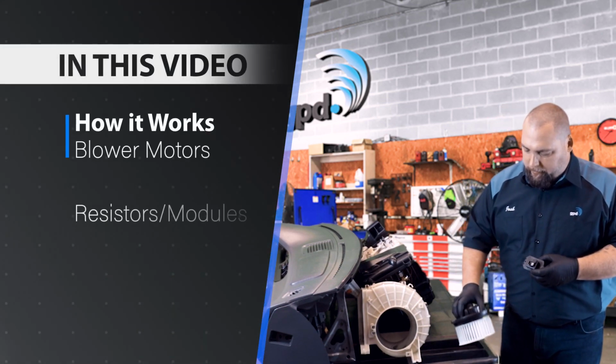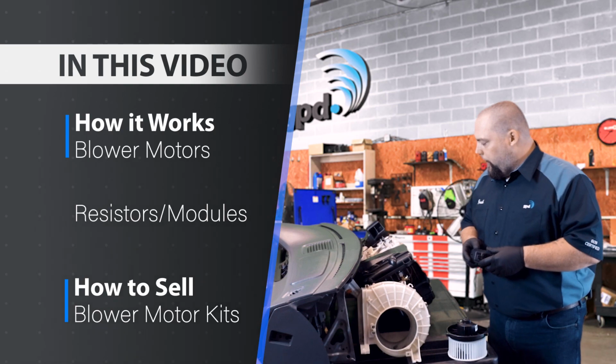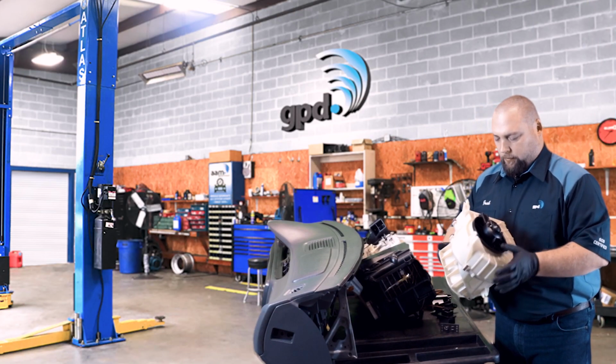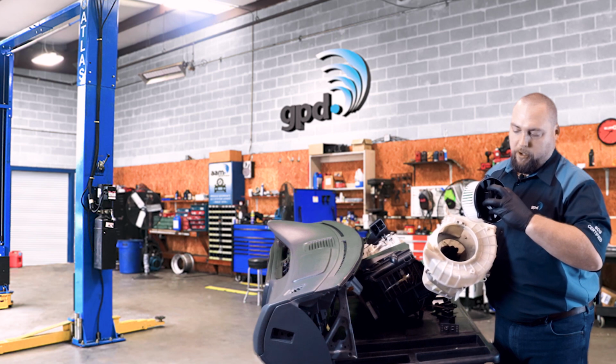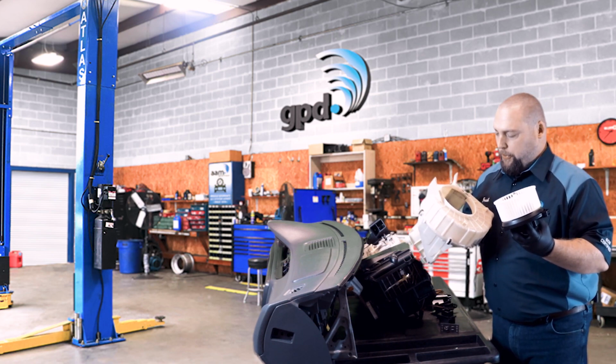In this video, we're going to be talking about blower motors, blower resistors, and modules, and just the different functions of each. This is your blower motor housing. It houses the blower motor, which is just an electric motor. This one's just got a 2-pin connector, and a plastic wheel that spins and pushes the air through your system.